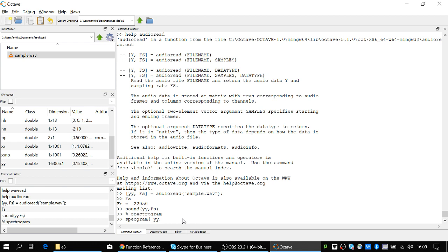Okay, so it's a Fourier transform. It maps the data from 0 to sampling rate on n values. And the most important part is the half of it. So if you have 1024 points, it means that this is actually mapped in 512 points, meaning that delta F is the sampling rate over the number of samples where you calculate the Fourier transform.